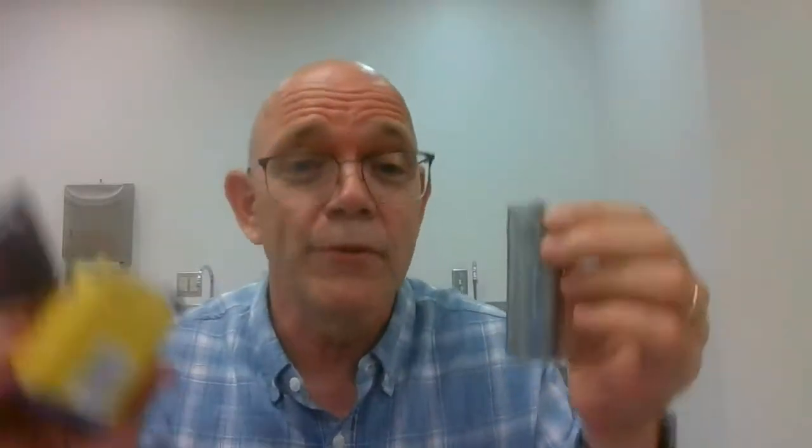Now, this is a lantern battery. They sell them for a lot of big flashlights. Usually these big flashlights had these before they came out with LED lights. And it is technically a battery, because inside of it you'll see there's actually 4 cells. These cells are very long, very big compared to some of the other ones. Let me see if I can get one out. There we go. Okay, and you have 4 cells. Once again, 1.5 each, so 2 of them make 3 volts, and the other 2 make 3 volts. So it's a 6-volt battery. If you look on the side, it says 6 volts.